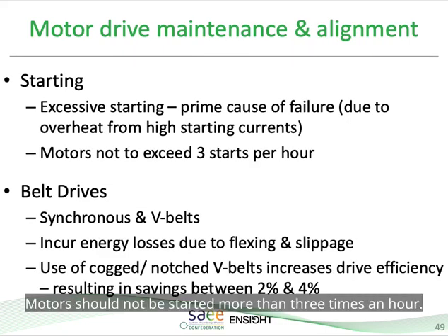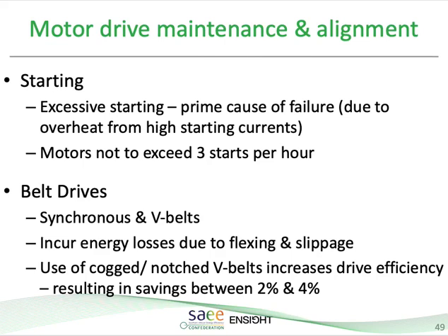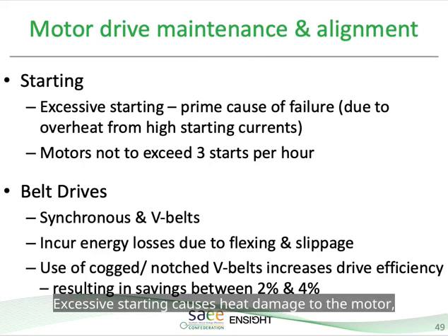Motors should not be started more than 3 times an hour. Excessive starting causes heat damage to the motor due to the inrush current heating the motor up.